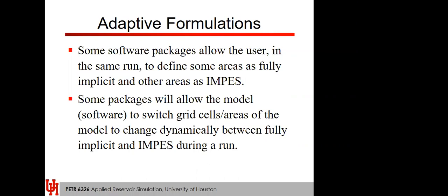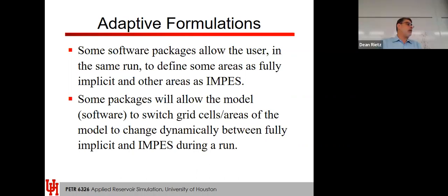Okay, thanks. They don't have to be. So again, it depends on the data. As I mentioned before, if you had a full field model, and let's say it's 50 years of history, you really don't care much about the early stages, so you could make them yearly time steps. I've done this before. Let's say yearly time steps for the first 10 years, where there's only one well and nothing much going on. You crank through those, and then you start to go to monthly time steps or quarterly or something like that.